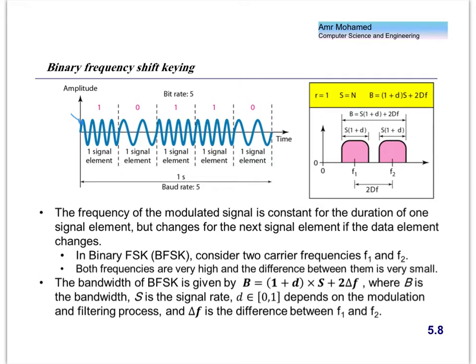So if we look at this composite signal, it's nothing but two ASK signals superimposed on each other, right? Because we can think of this part as an ASK with frequency, let's say this is frequency F2 and this is frequency F1. So it's as if we create two ASK signals, one using F2 and one using F1, and then we combine both. And that's one idea that we will use to implement binary FSK.